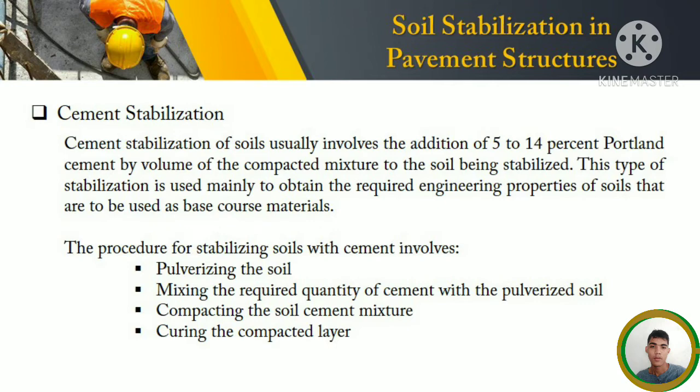Under the cement stabilization, we have a procedure to follow, such as pulverizing the soil, mixing the required quantity of cement with the pulverized soil. The third one is compacting the soil-cement mixture and curing the compacted layer.